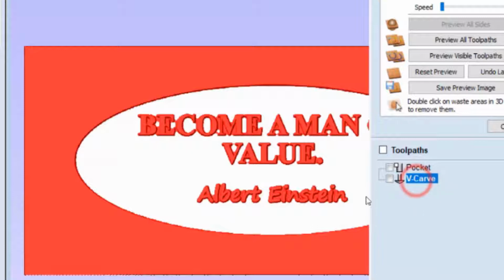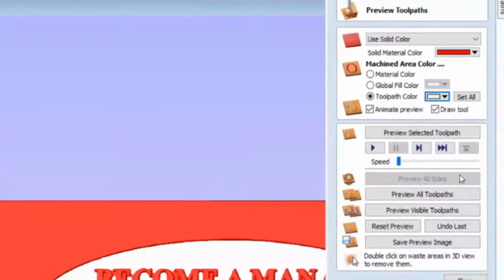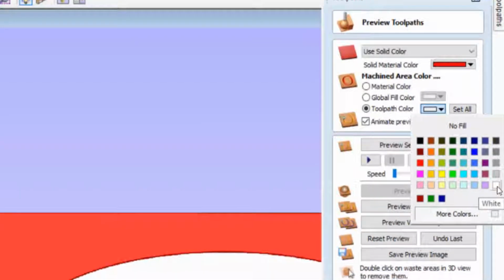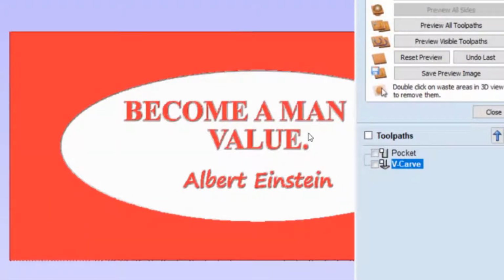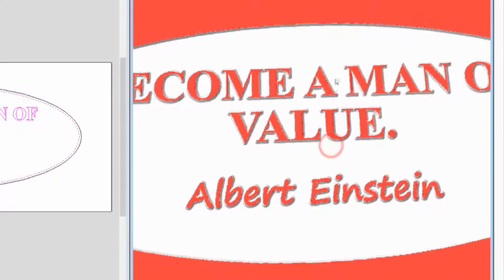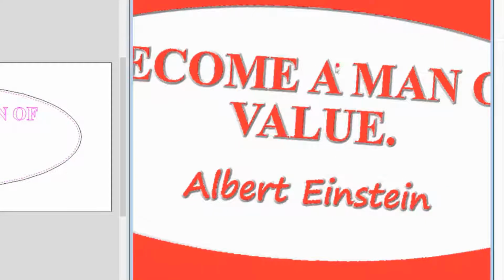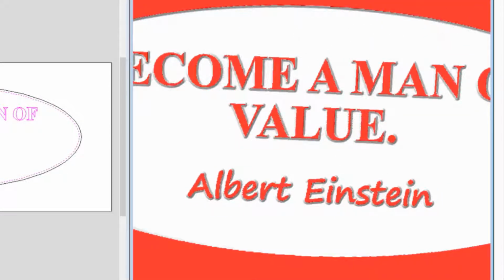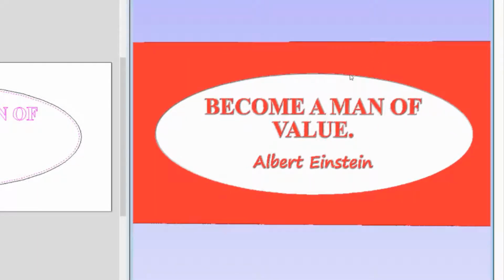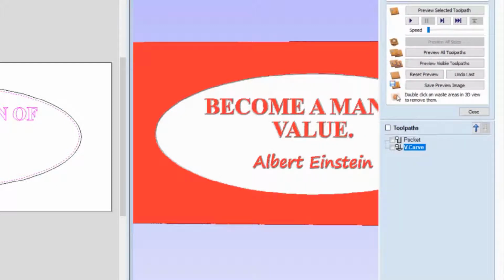So the V-carve bit is going to remove the rest of the red. We're going to turn that to white as well. So we're going to go over here where it says toolpath color. We're going to select V-carve, and then we're going to select the white color. And that's pretty much the finished project here. So we're going to get closer here. As you can see, there's a bevel, and this is actually the color of the material. The material is actually going to be white. We're going to be using PVC sheet, so it's actually like a plastic type of material. Same stuff that they use PVC pipes with, most likely. And that's it.